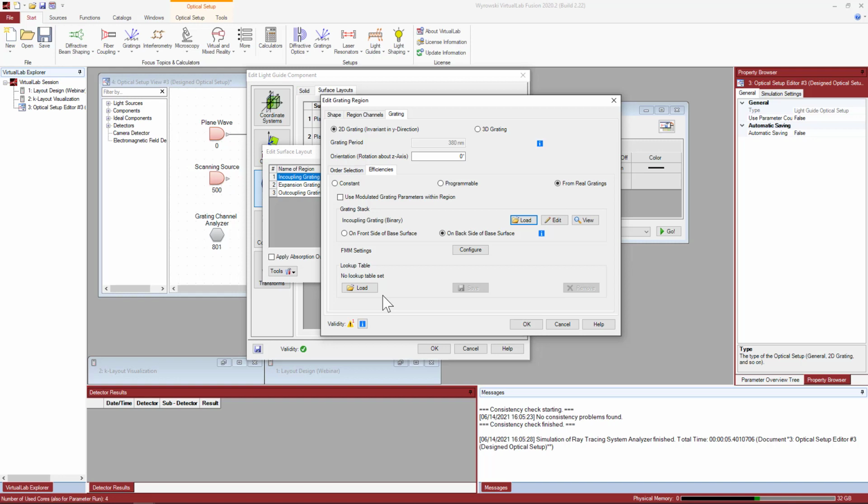The information of how that grating transforms the field for different wavelengths, for different incoming directions, and for different predefined orders would be stored after the simulation is run once, so that when we repeatedly perform simulations with this system, that FMM rigorous analysis of the grating does not have to be repeated, and we save on simulation time. This is an extremely powerful concept.